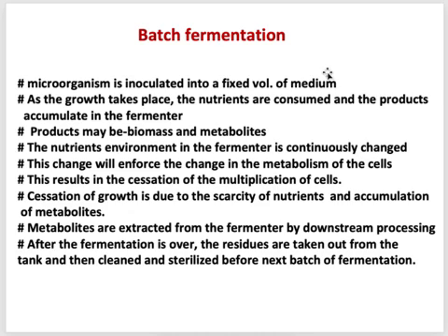In this case, we do it batch by batch. So what do we mean by batch here? Say you will do fermentation by a batch system. You will put the microorganisms and your liquid media, that's the substrate, into the fermenter, and you just turn it on. The fermentation process will go on until it stops.